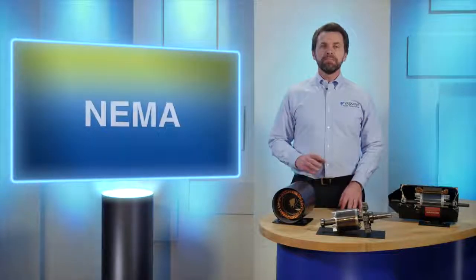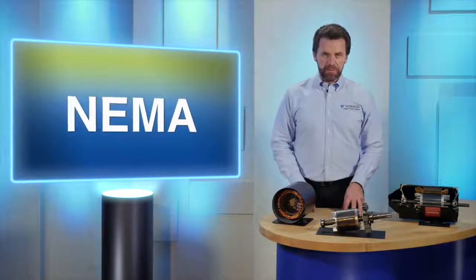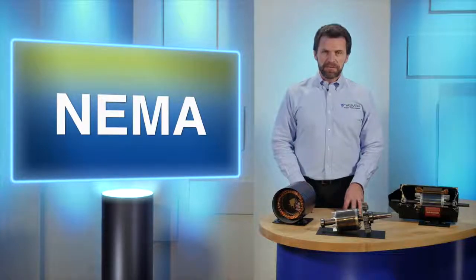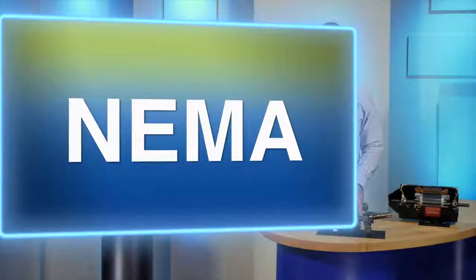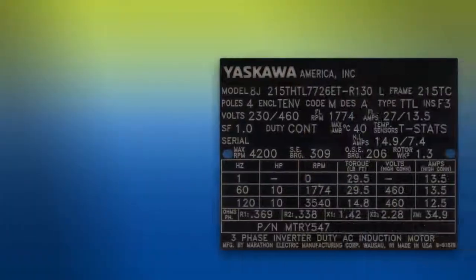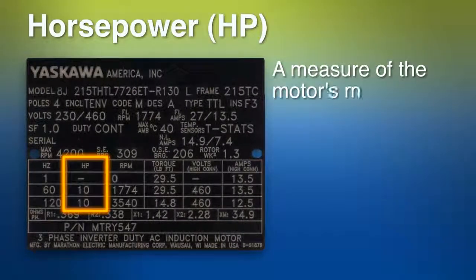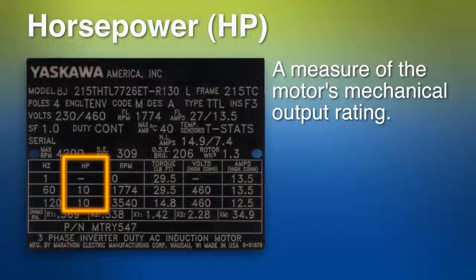In this next section, we will give you an understanding of the information on an induction motor nameplate. In North America, NEMA also establishes the standards for the information provided on the nameplate. This information is vital to determining the motor's characteristics. Let's look at a typical nameplate. Horsepower is a measure of the motor's mechanical output rating and its ability to deliver the needed torque for the required load and at the rated speed.